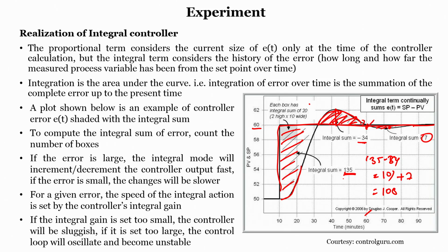One thing we have to understand: using op amps, we can do any kind of operation. Integration we can do, differentiation we can do. If you recall, the way of doing integration is simply by using a resistor and a capacitor, which does an integration operation. The PI controller is a combination of integration as well as proportional. We have to take an adder which adds the proportional controller and the integral controller. The addition of these two is nothing but my PI controller.